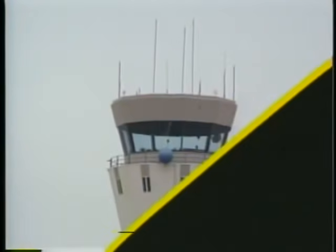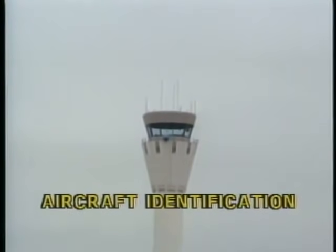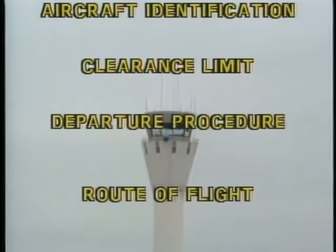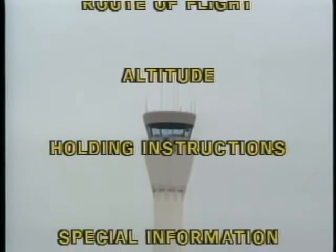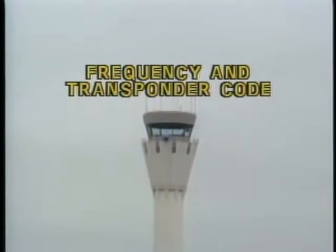To assist you when copying clearances, they are always given in a particular order, beginning with the aircraft's identification, then the clearance limit, departure procedure, route of flight, altitude, holding instructions if appropriate, any special information, and frequency and transponder code.